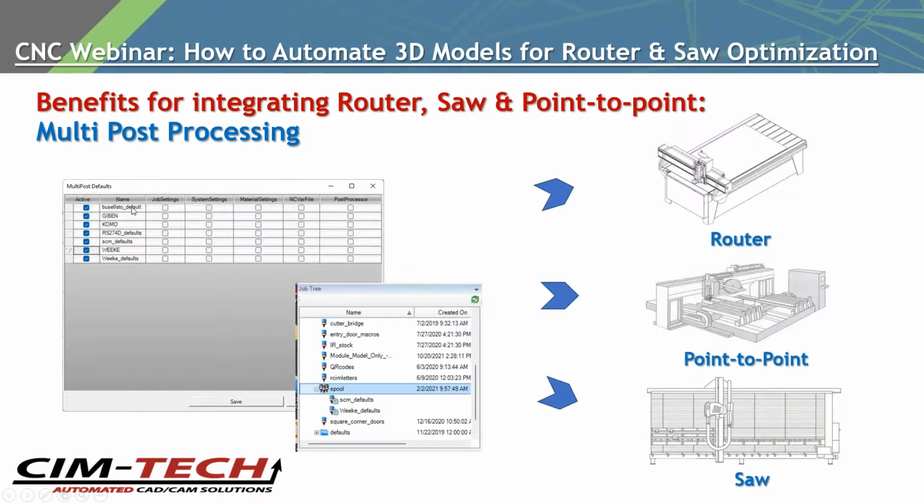With our multi-posting, it allows you to use many features of the RouterSim database, including the material settings, for example. So you might have one machine that has material that's long in Y and another machine that has material long in X. So when you check these boxes, which machines you want to output them to, and this is just an example of some of the post processors I had on my computer, you could have it use all the settings, including the material settings and the post processor, and all the job settings would be like what the NC code file extension is.